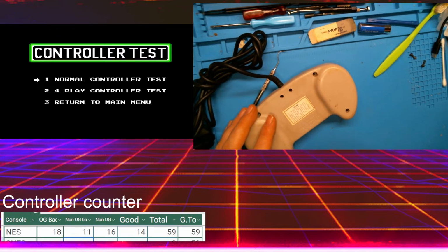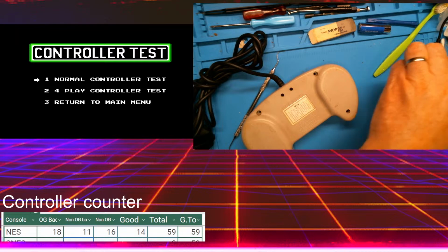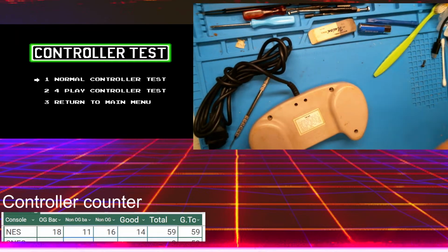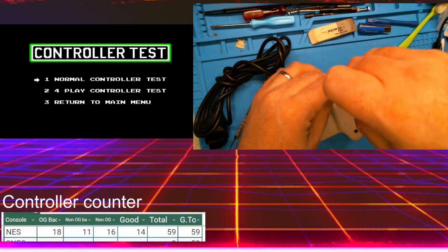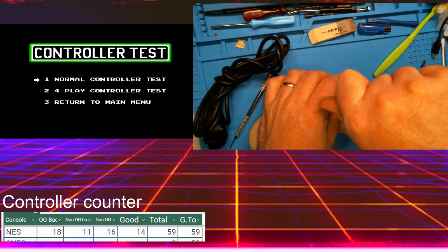Analog drift and modern controllers go together like peanut butter and jelly. That's right. The best analog stick ever is the Sega Saturn's pad. If you've ever taken that one apart, it's all magnetic sensors. It's Hall sensors all the way through.